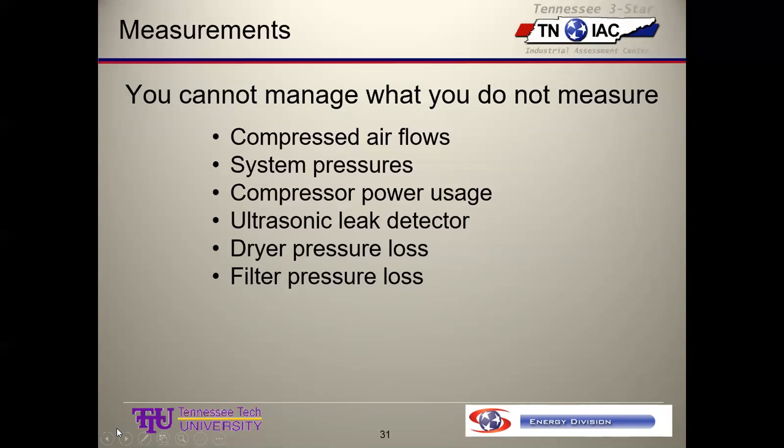We can try to find and quantify leaks with ultrasonic leak detectors. And now we have even visual type leak detectors that I will bring one of those to class and demo it. We can have dryer pressure loss and filter pressure losses.